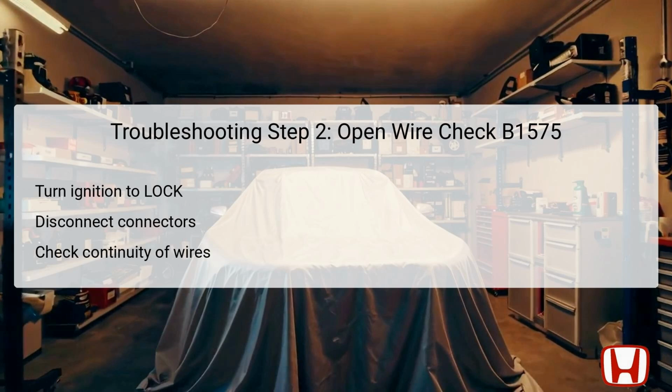Start by turning the ignition switch to the lock position. Next, disconnect the 14P connector from the automatic lighting control unit and the 5P connector from the automatic lighting sensor.